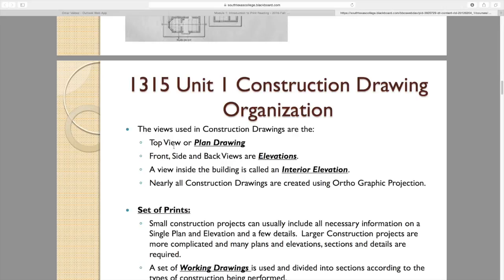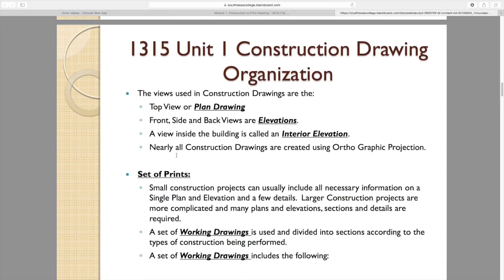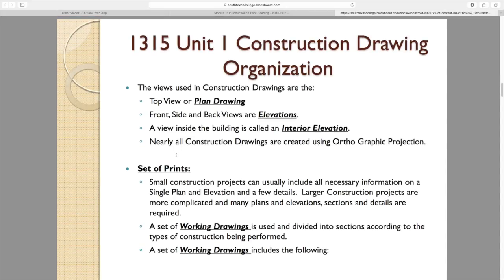So imagine you have one of these machines, what they call drones, and you fly it on top of your house, and you record straight down. What you see of your roof, that's a plan view, an orthographic view seen from the top. So any drawing that you see from the top, they're plan drawings or plan view drawings.